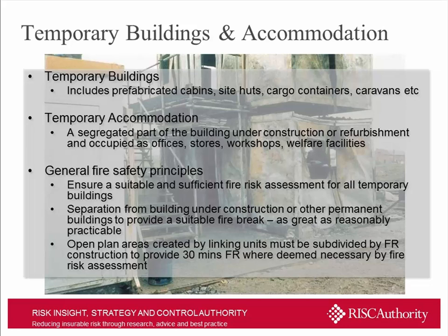And if you're going to put cabins within the building under construction, for them to have a degree of fire resistance, so that they're difficult to ignite in the first place. But also, should there be a fire, that they'll effectively contain the fire for a sensible period of time. The code makes requirements for 30 minutes fire resistance.